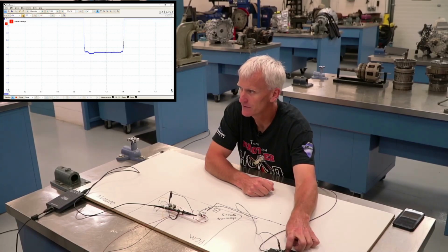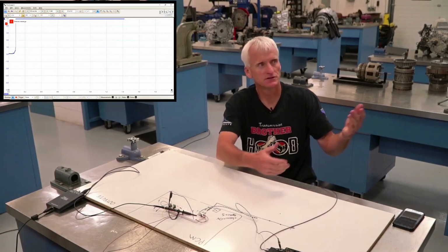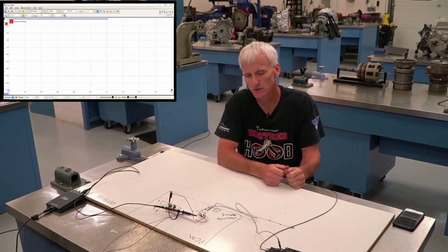Now you can imagine how the computer can figure out when you're in a certain manual valve position, because it's going to see it go either high voltage or low voltage. And once it sees low voltage, it knows there's pressure there, and it knows that switch closed.